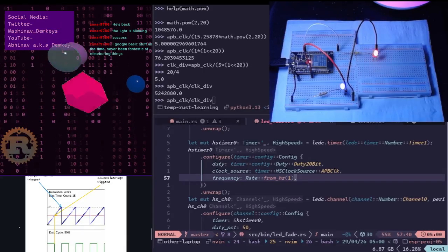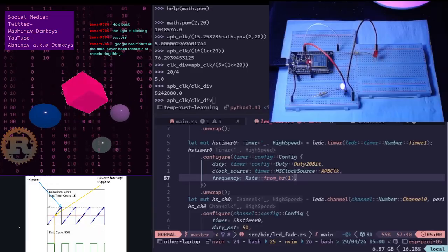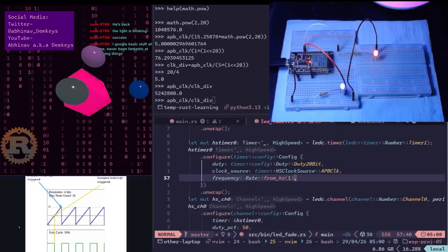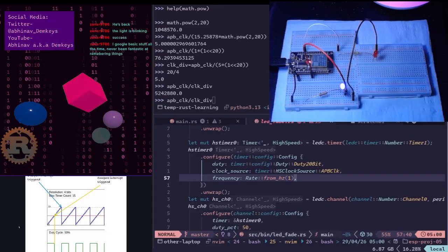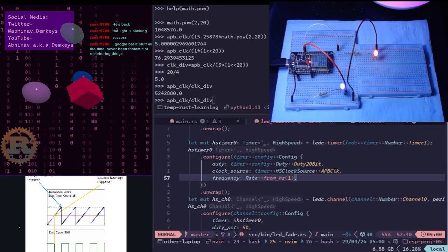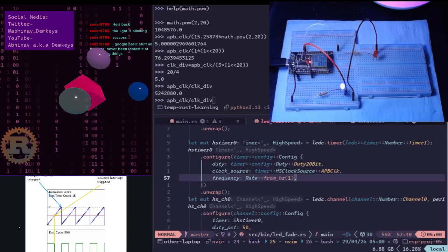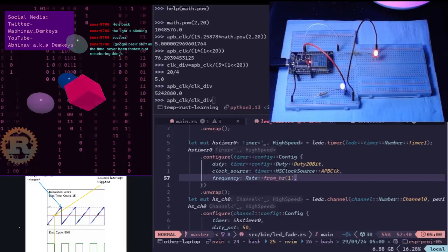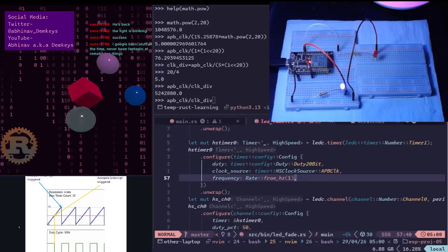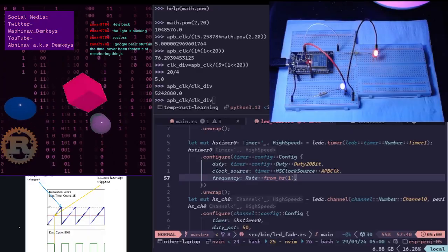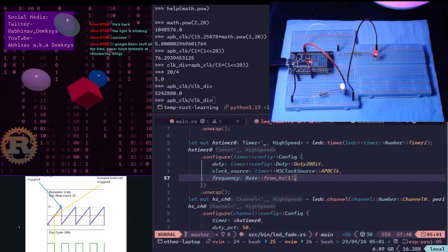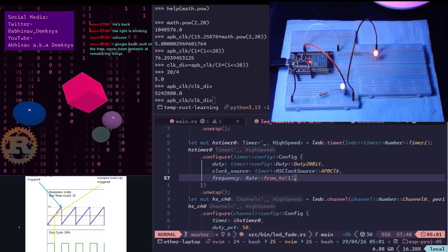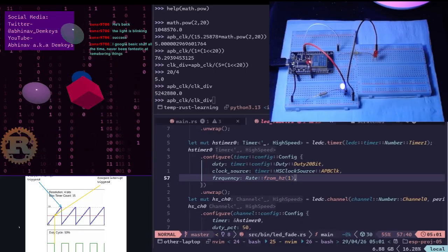How the fractional part changes the max value. This is where it gets clever. Since a digital counter can only count whole numbers, you can't count to 10.5. The hardware uses a fractional divider, often a first order sigma delta modulator. If you set your divider to 10.5, the hardware cheats by changing the max value of the internal counter dynamically. In cycle 1, the divider counts to 10 and then sends a pulse, and in cycle 2, it counts to 11 and then sends a pulse.